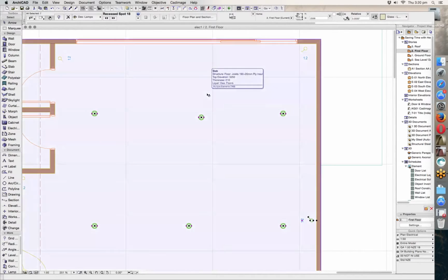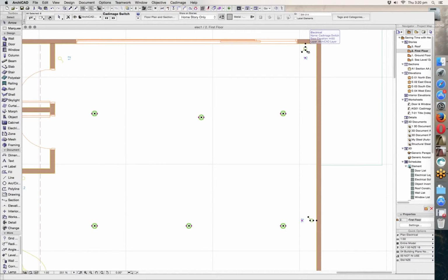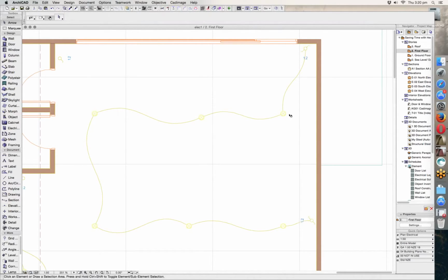So now that we want to add something to our circuit, simply select the wiring and delete it. As soon as you do that, the wiring goes away and it automatically selects all of the things that were wired. So now we can add to our selection the thing that we want to add. We want to add this switch in this case. And now I go through and press place circuit again, and it rewires everything up, including the new thing.